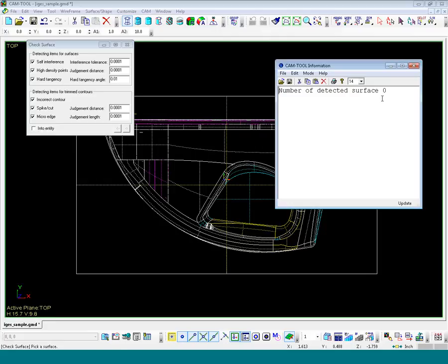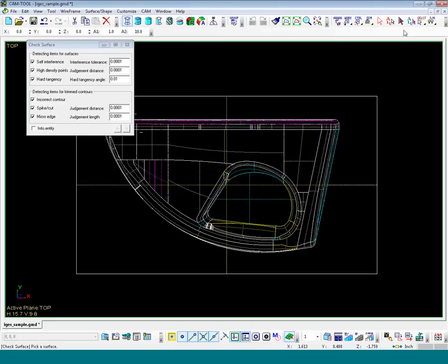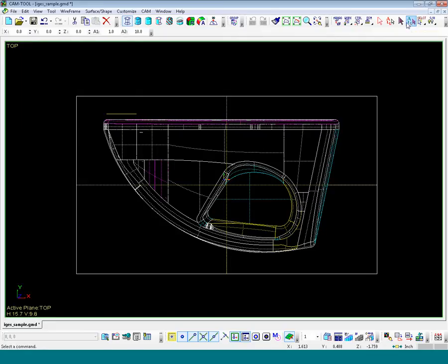That's not always the case. But as we were told earlier, not everything that this detects is going to be an error. Some things just maybe slow down toolpath creation or things like that. Not necessarily something physically wrong with the geometry. If it says warning or error, then obviously you're going to have to do something to fix it. Usually getting your engineering department involved at that point would be a good idea. If we use the Select None, it'll clear off some of these boxes that we don't want on the screen. Sometimes even Escape will work.